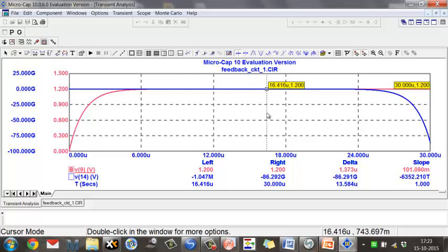So it eventually goes to, it's an ideal op amp. There's no limit on how high the voltage can go. And what is the positive feedback doing? It just keeps on building it up. There's no limit to the output voltage here. It just keeps on going, and eventually, of course, it's going to giga and all that, right? So the steady state analysis is not giving us the right answer.